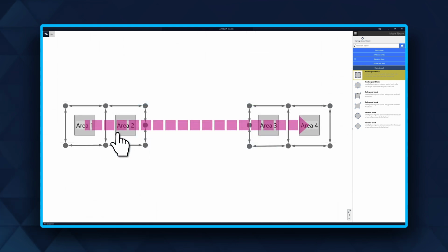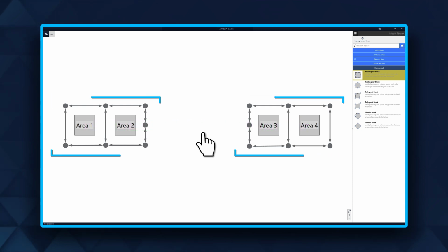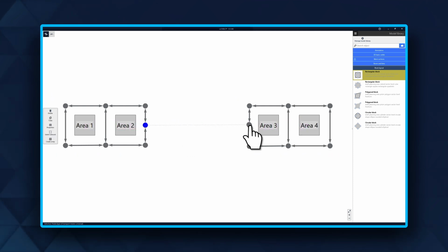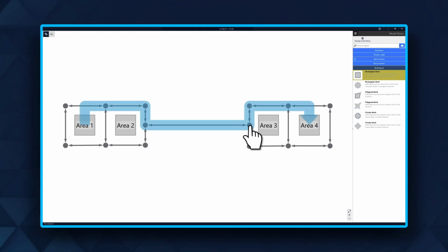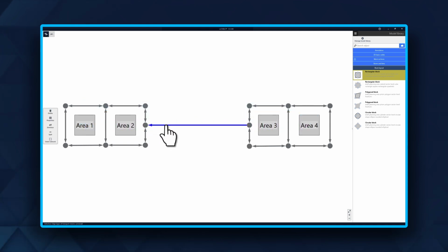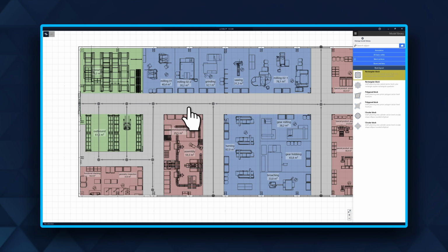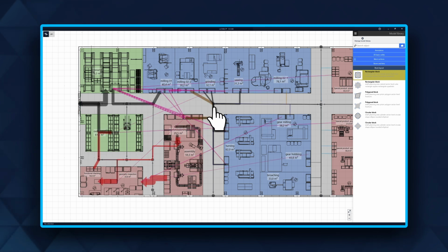When you see a pink dashed line, it signals a routing failure, typically caused by one of two issues. Either you have disconnected sections in your transport network, or there are problems with the set transport direction of the net edges. You should avoid separate network sections. Here you can see what happens.